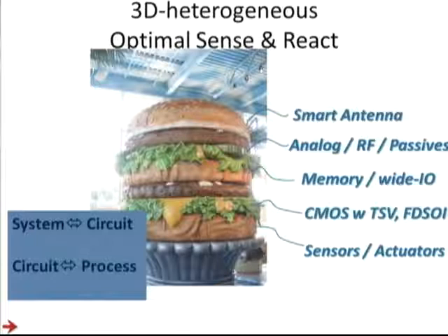But it also enables very high performance once you use forward body bias, or it can pretty much shut itself down in terms of leakage when you use reverse body bias. And all of this can be and must be controlled from the system level at the software level.